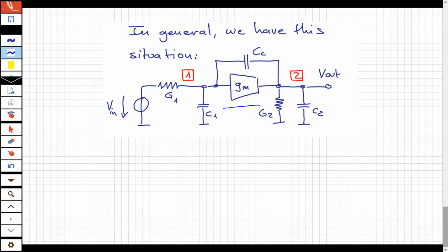So from here to here, you have a negative gain of AV, minus AV, so minus some voltage gain. And this is actually, if I use these compound values here, just minus Gm divided by G2. So the higher the transconductance, the more gain you have, the lower the output conductance. So the better your transistor current sources are, the more gain you have.